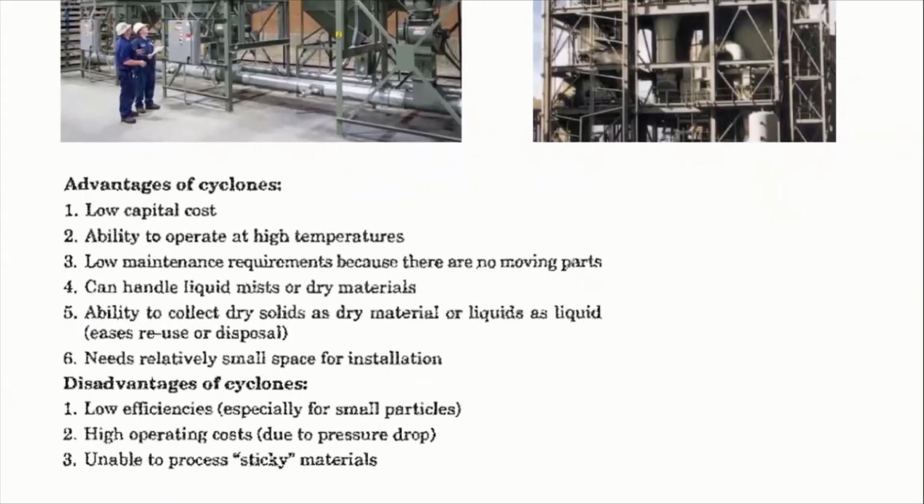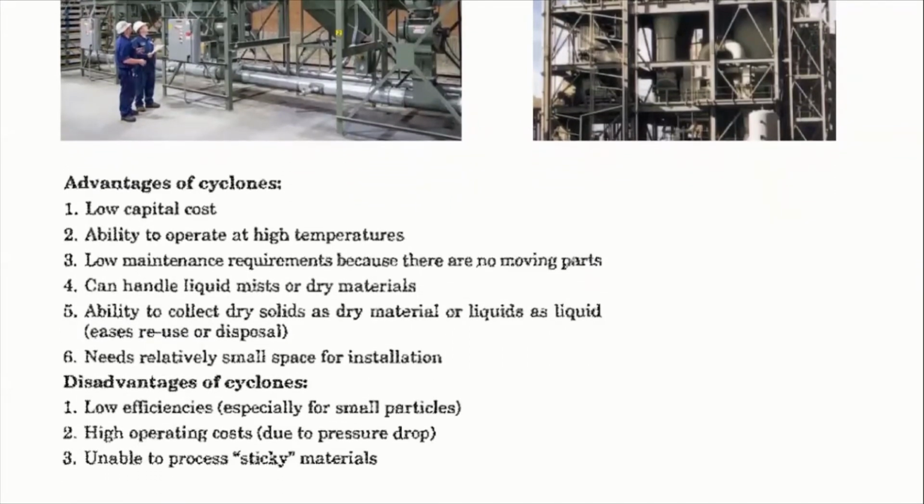If you think about the structure of the cyclone, it's just composed of a case, right? A stainless steel or metal case. We don't need to add any other rotational parts, right? We can just build it as is, and we just need to worry about leakage. There's no leak for the setup, right? That's why it has very low capital cost. We can even build a homemade cyclone, right?